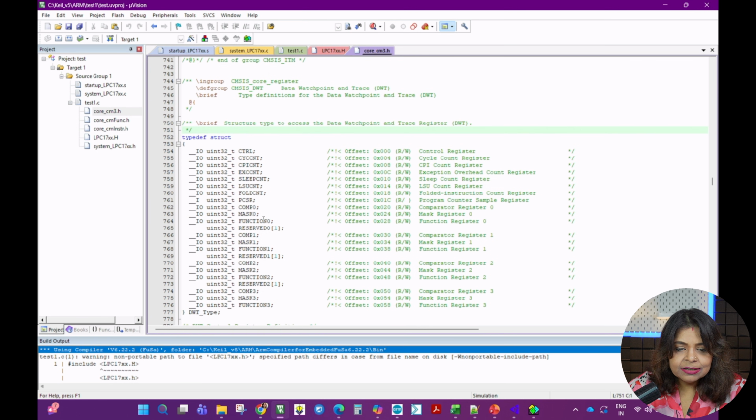Semiconductor vendors like NXP, ST, Texas Instruments, Microchip, Samsung, even Qualcomm with Snapdragon, any higher-end or lower-end vendors, buy this IP core from ARM and put their own set of peripherals. Peripherals can be timers, I2C, SPI, UART, Ethernet, DMA, PWM unit, anything. They put those peripherals onto this core, develop a microcontroller, and release it to the market. And those devices are supported by MDK.